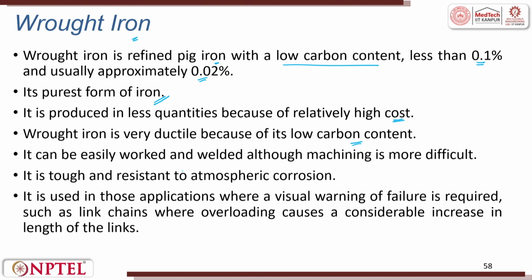It can be easily worked, although machining is very difficult. It is tough and it also has corrosion resistance. It is used in those applications where a visual warning of failure is required, such as link cranks, where overload causes a considerable increase in the length of a link. So, slowly it will get stretched because it has the ductility property.